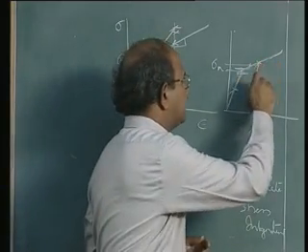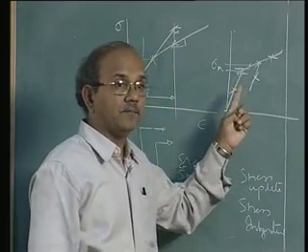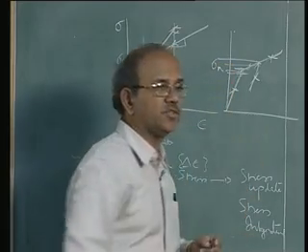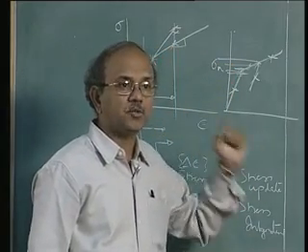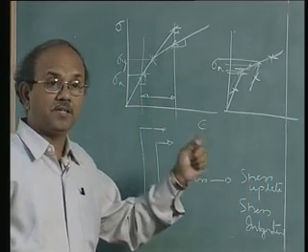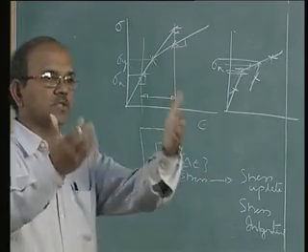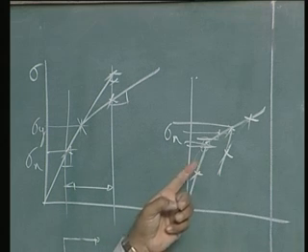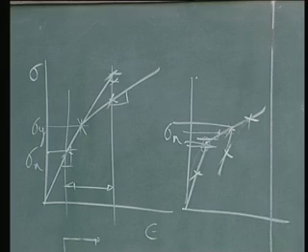Then my sigma y is not this initial sigma y, but what has been updated. So, in other words, I have to update the yield strength of the material as well. It's a very important point that yield strength of the material is also updated. So, when I update the stress, this goes along with it. Is that clear? That is why I said sigma n. So, from here to here, the procedure is exactly the same.